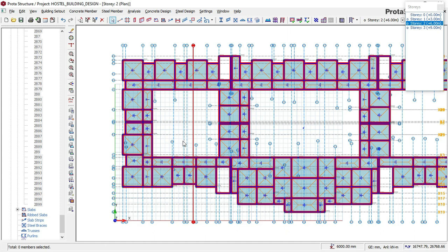Okay, so let us hold on for it to finish up selecting. When it's done, this arrow cursor symbol will change to a square, and that's when you know that it has finished pasting the wall load on the beams. We will now go ahead and remove the wall load again on the perimeter of the courtyard, which we did again on the first floor. Okay, so let's just hold on for it to finish up just now, and then we'll move on to the next.